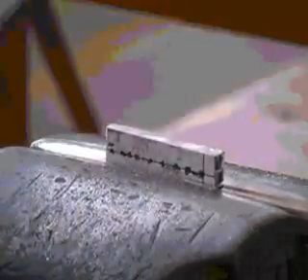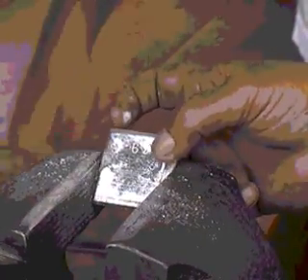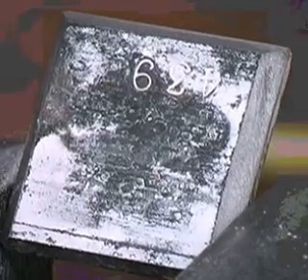Since a lot of material has to be cut, first we'll remove some material using a hacksaw. After cutting, a mark of 3 mm is made on the side and the face. This distance is used to make an angle of 45 degrees by filing. This shows how to use a file. So this is how a job will look after filing.